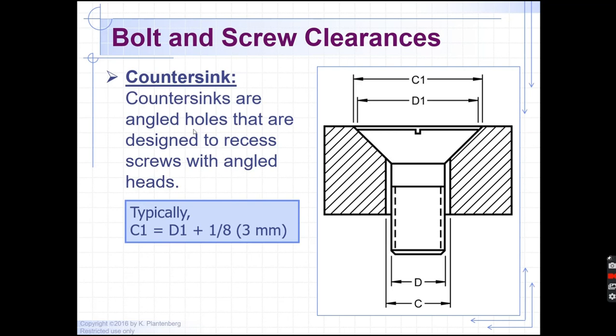Countersinks are angled holes that are designed to recess screws with angled heads. Again, typically this outer portion here is the diameter here plus an 1/8.